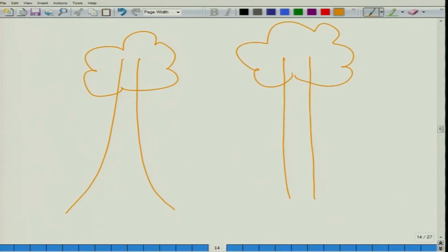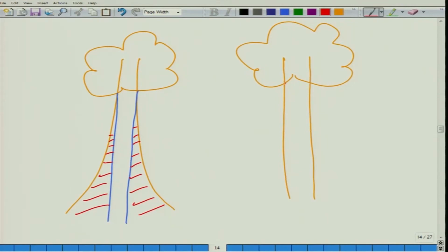If you wanted to use the wood for sawing purposes, and you made a cut here, because we essentially require very straight sheets of wood, we would be losing this wood. Whereas, in this case nearly all the wood would be utilized very easily.